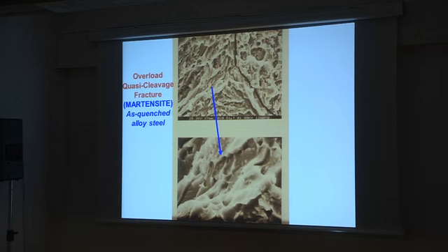And that can go to an increase of fracture toughness of even 10 megapascal square root of meter, which is not a mechanism of increasing the ability of a metal to withstand stresses, because we are passing from 35 to a maximum of 45 megapascal square root of meter.